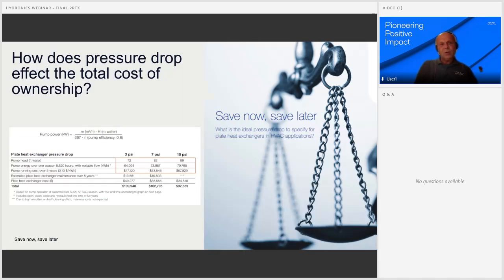What we can see, of course, is that the pressure drop in combination with a higher investment for a pump has an enormous effect. We have created a booklet where we explain the whole situation with different pressure drops. And of course, if we go for a higher pressure drop, there are certain things we have to know as the basic. Higher pressure drop means less investment in heat exchanger because it gets smaller.